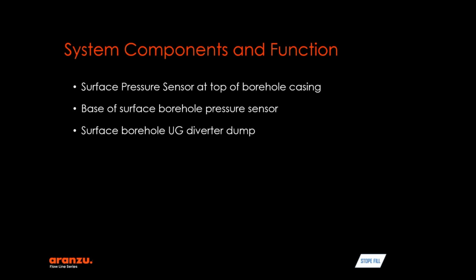The pressure sensor at the base of the surface borehole is located 20 to 30 meters away from the borehole casing breakthrough. This pressure sensor indicates the paste column height in the borehole and the system pressure at that point in the underground retic system.